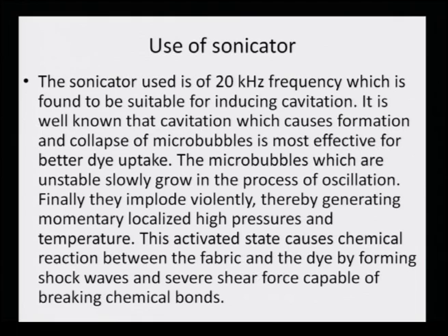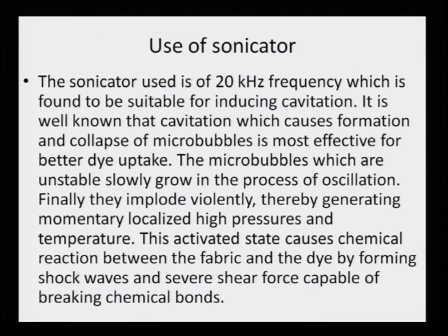Now, time and again we have been talking about the Sonicator, and we have understood that this agitation mode definitely helps in dye uptake. What else does it do to the fabric? The Sonicator used here is a 20 kilohertz frequency machine, which is found to be suitable for inducing cavitation. It is well known that cavitation, which causes formation and collapse of microbubbles, is most effective for better dye uptake.